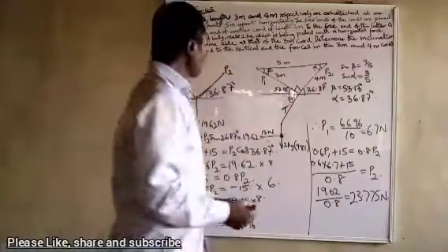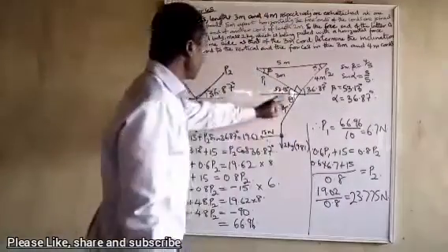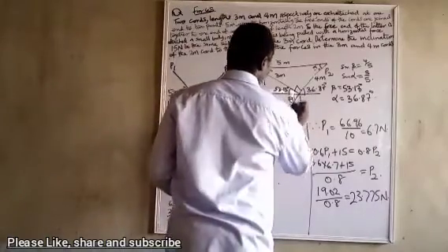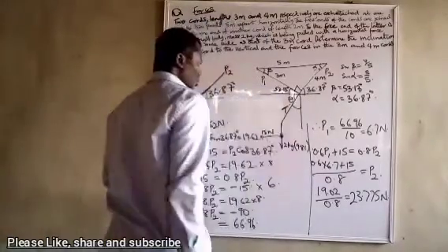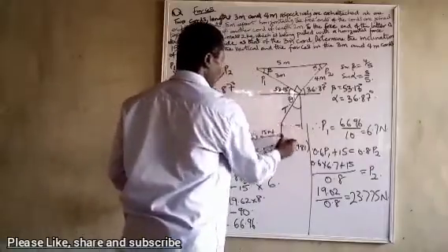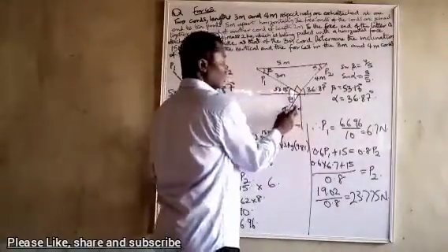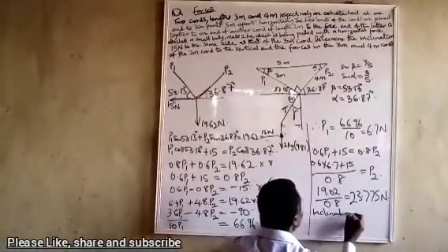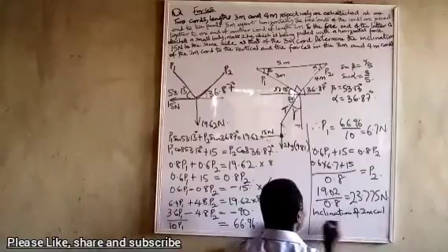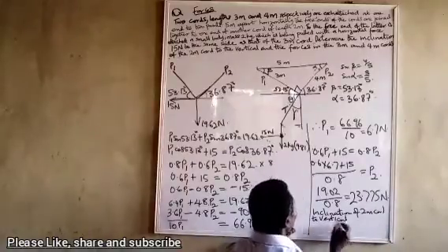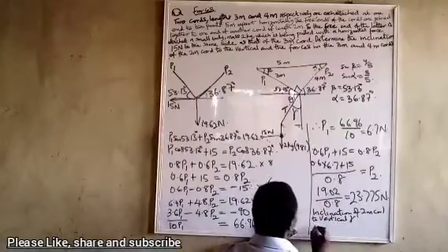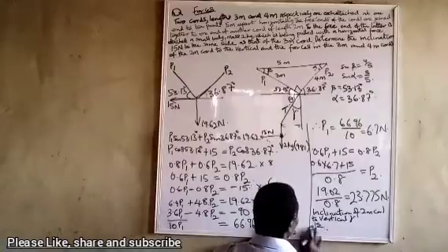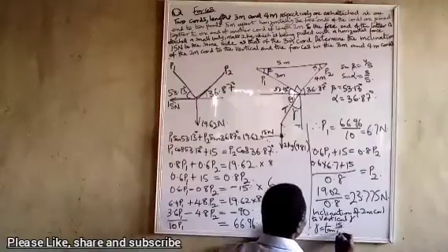And that is. So now we are also asked to determine the inclination of the 2 meter cord, this one, to the vertical. This is what you're asked to find. And to do that, I know the component of this place, I know this one. So, going to this place, let me call it gamma. So, inclination of 2 meter chord to vertical, gamma. I can find that by saying 15 over 2 times 9.81, gamma equals arctan 15 over 19.62.